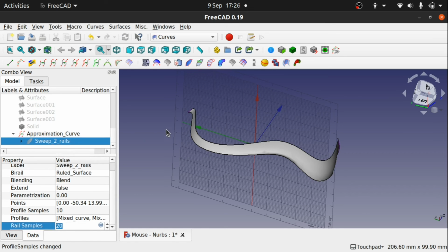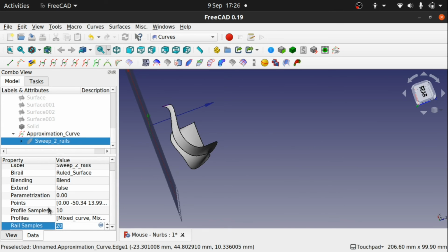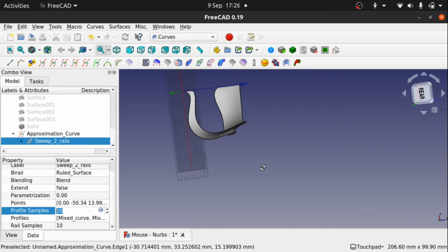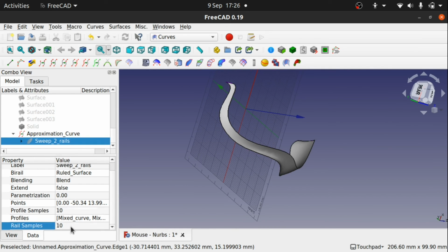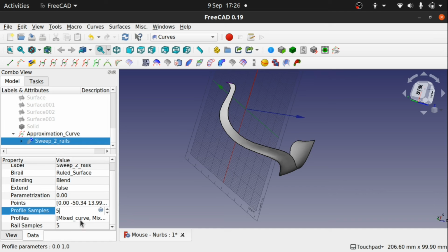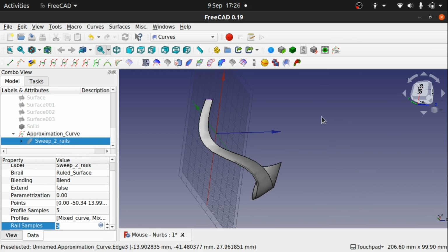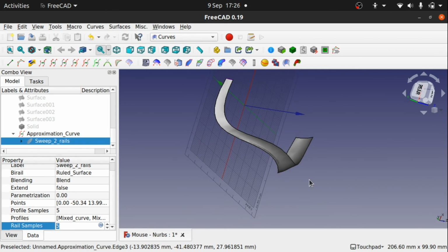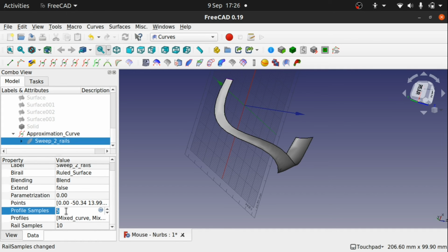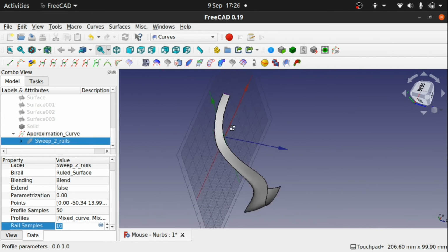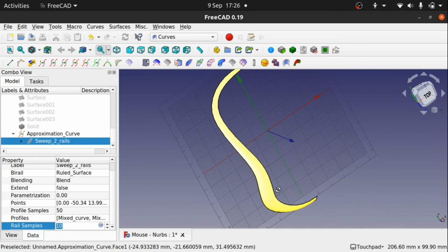And we can see we're starting to get problems. That's curved over there. So if we've got something like that, or if I lower this to say 10, and we've got some obscure features happening on this, I'm trying to get it so it goes into some kind of error where we have problems with this actually coming off and up into 3D space, but it's not doing it. If we have problems, then we just increase these like 10 and increase this to say 50, and we can get that conforming more to the shape that we so desire.